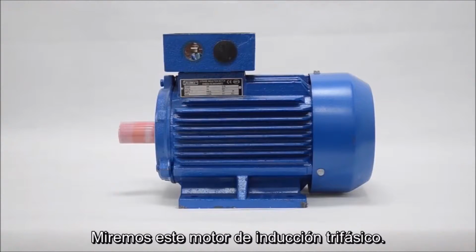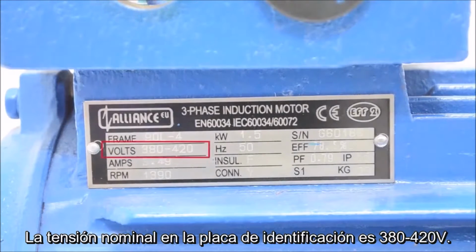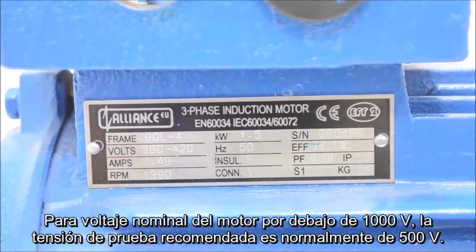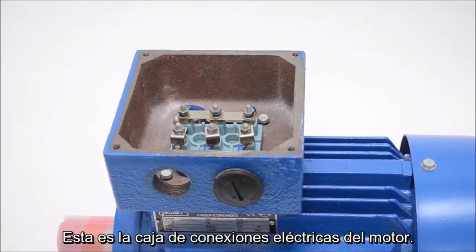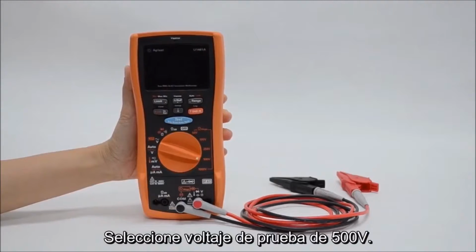Let's look at this three-phase induction motor. The rated voltage on the nameplate is 380 to 420 volts. For motor rated voltage below 1000 volts, the recommended test voltage is normally 500 volts. You may consult the motor manufacturer for the recommended test voltage. This is the electrical junction box of the motor. Select 500 volt test voltage.